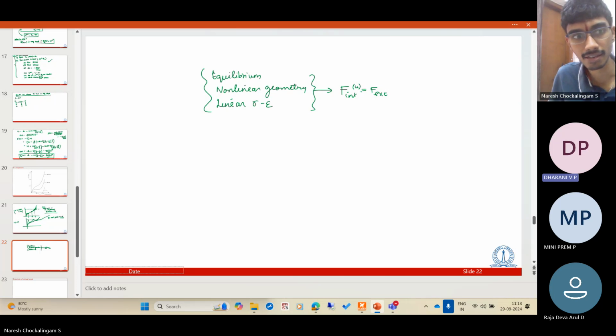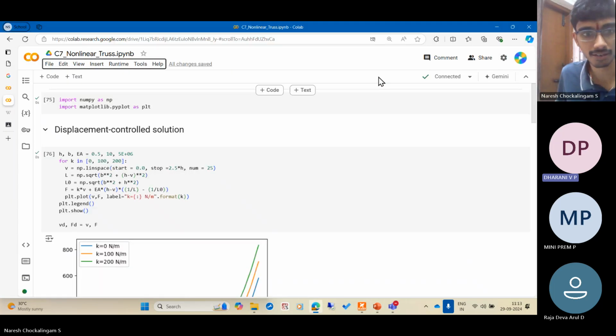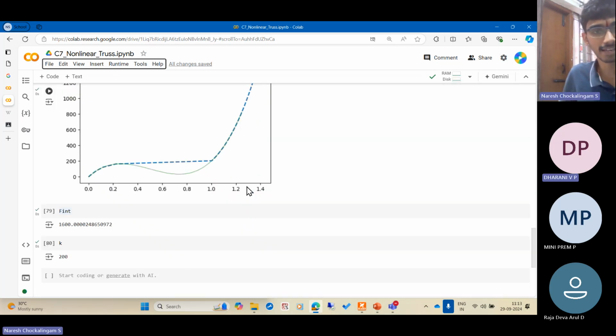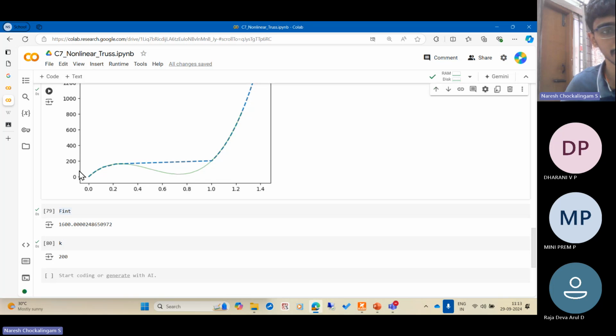Yes. In the snap-through region, the structure is accelerating, sir. Yes, we are not modeling it correctly. If we do a dynamic analysis, it will accelerate. But in this case, what is happening is it's not able to find a static solution nearby. So if you remember when I started, I asked how many solutions we have. If you give a force, initially we had 3 solutions. But since we are increasing the force gradually from 0, it always captured the closest solution.